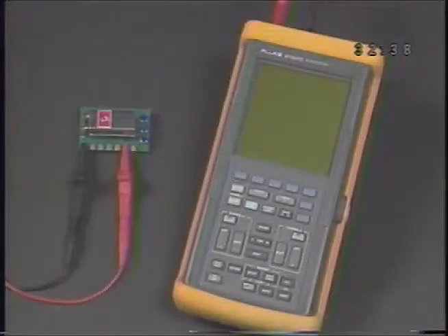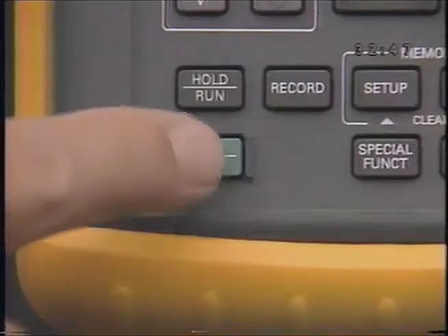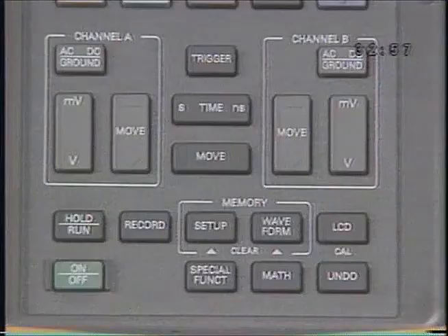Set the simulator up as shown in the simulator exercise for Lesson 2 in your workbook. Attach Scopemeter's Channel A probe and ground lead and turn Scopemeter on. You're going to use Scopemeter's Auto Set feature to adjust the levels on this signal, but first, you have to adjust the settings for Auto Set.